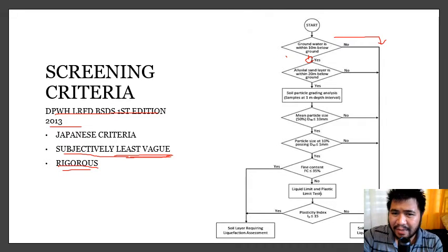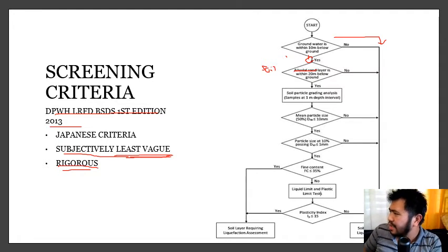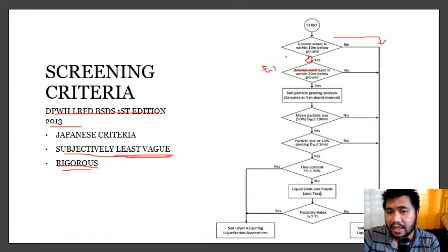This is a bit of a misnomer because this is better spelled out as soil layer, not alluvial sand layer. It just complicates the definitions here. How do you determine if the soil is alluvial sand? What is your specific criteria for saying the soil is alluvial sand?